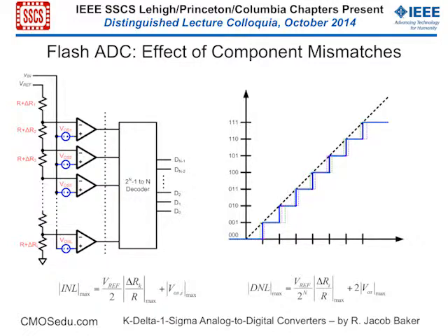It's not like ones or twos of millivolts of offset or difference between transistors. You can get nowadays 50 plus millivolts mismatch between two transistors easy, and that's with a 250 millivolt threshold voltage. So the mismatches and input referred offsets are becoming more and more of a big deal, and also the resistor mismatch. This topology is great for low resolutions, but again, designing a comparator with a low delay and a high enough gain to resolve, even for 6 bits, is becoming challenging in the newer technologies.